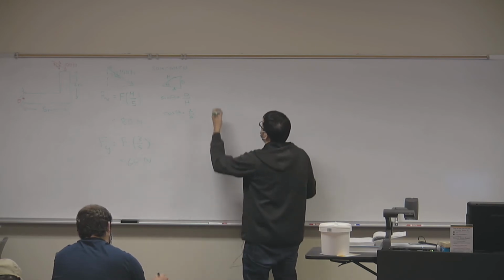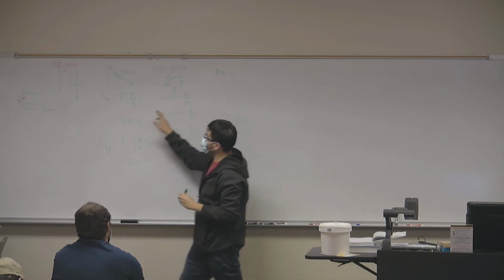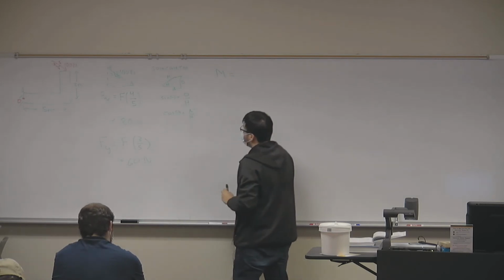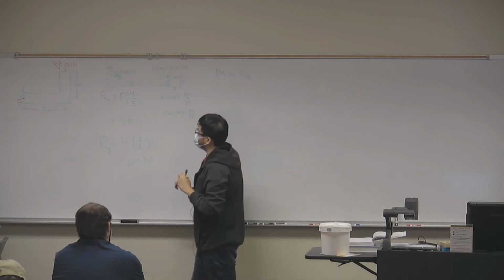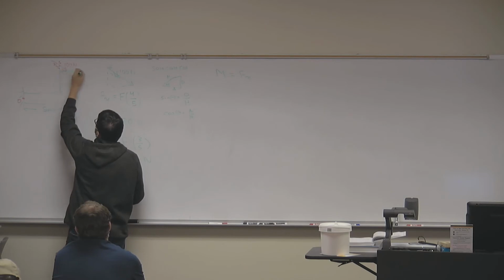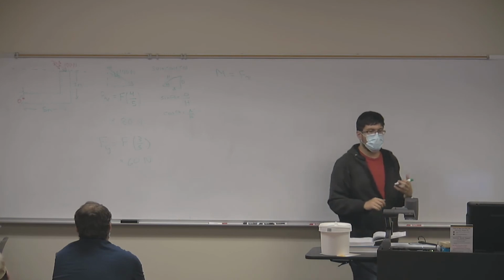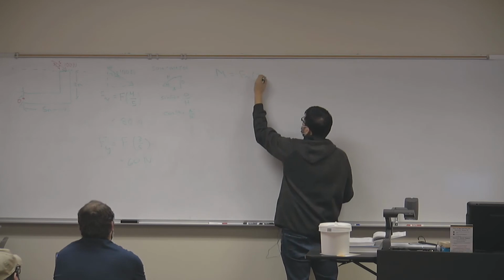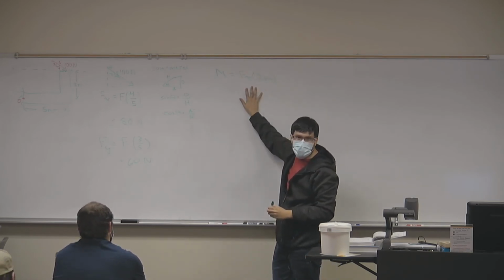Now let's just calculate the moment. The moment about that point should be equal to the moment that each component has about the same point. So let's start with the x component. The moment is equal to the x component times what distance? We have my x component of the force. It acts on the same point. That means that my line of action is this horizontal line. So what's the distance between the point and the x component that I would use? Sorry? 2, correct. And would this be a positive moment or a negative moment?